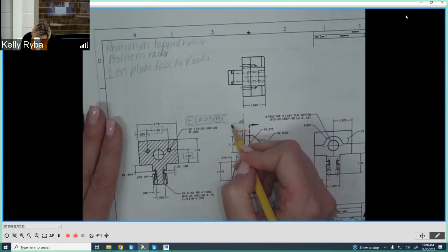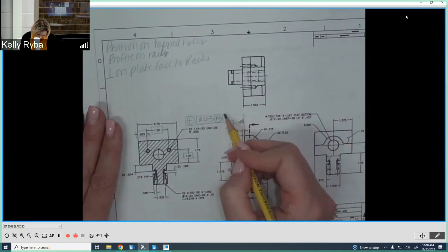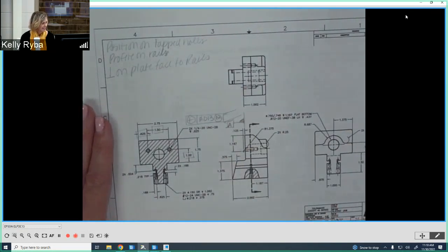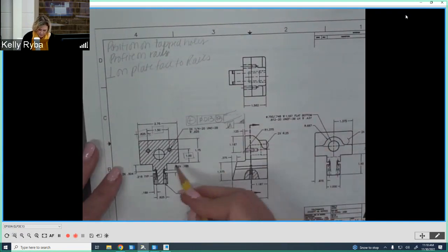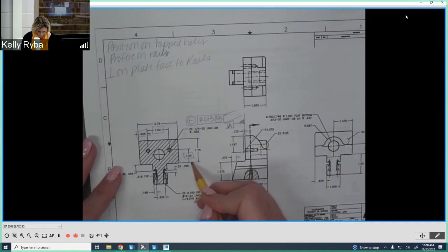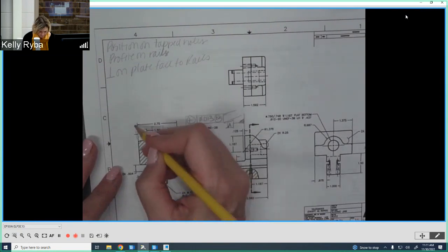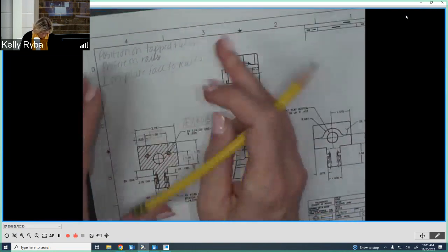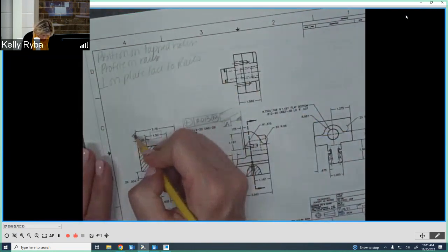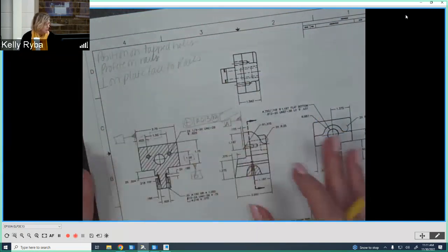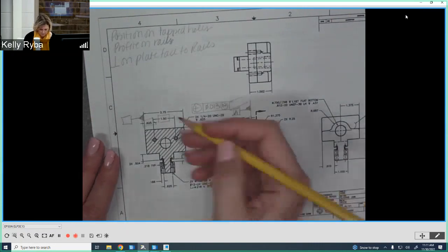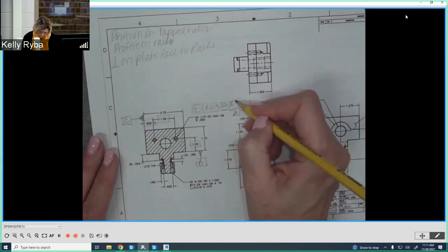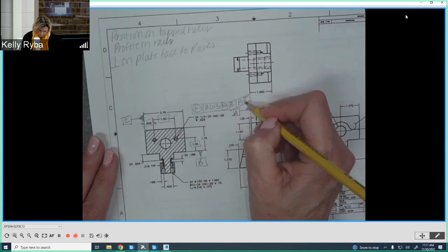So this is going to be our datum. We'll call it A. We'll kind of go up with our datum scheme here. That's going to be datum A. Datum B is going to be this surface here, because that's the dimension up, and then datum C, not in line, got to be off. Remember, don't put your datums in line with any dimensions, otherwise it's going to assume the center plane of something, and that's going to be C. This will be A, B, C. Okay?